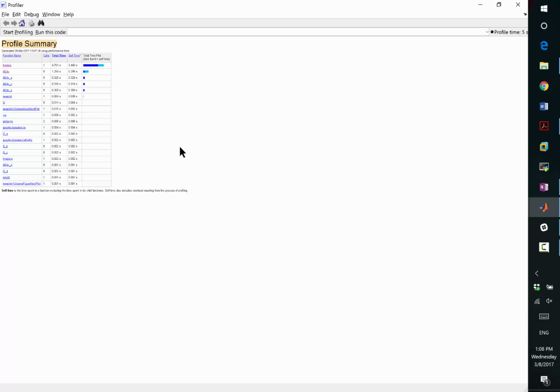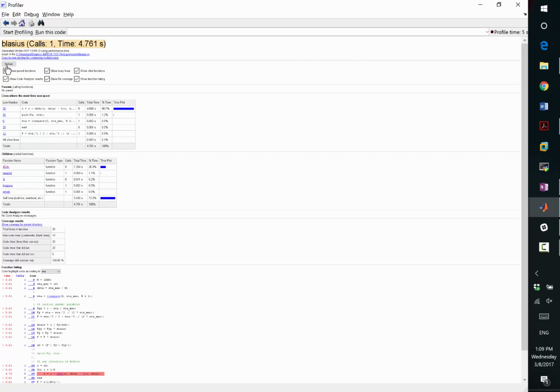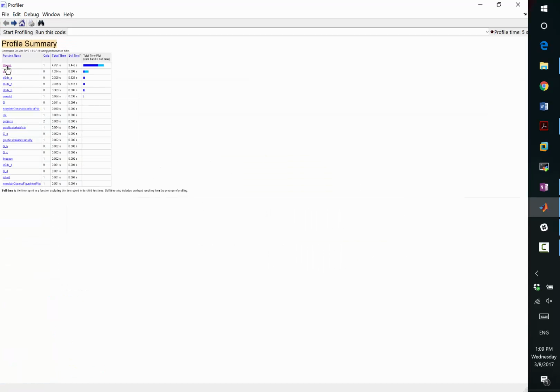Then we started by asking whether it is possible to have a self-similar solution, because that would simplify the analysis and lead to understanding a lot faster. A self-similar solution means that when you shift the streamwise location from one position to a little bit downstream, the solution looks exactly the same except for a scaling.